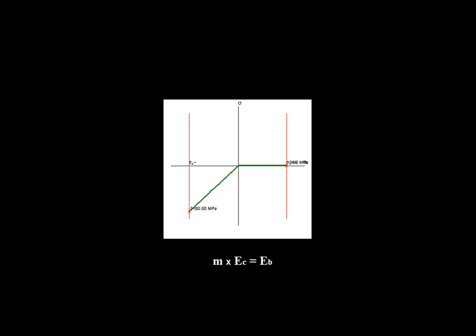Indeed, for the same deformations, the normal compressive stresses exerted by the bearing support become smaller. Conversely, as m decreases, the part of the bearing support affected by the compressive stresses decreases in size, although the stresses exerted become greater.